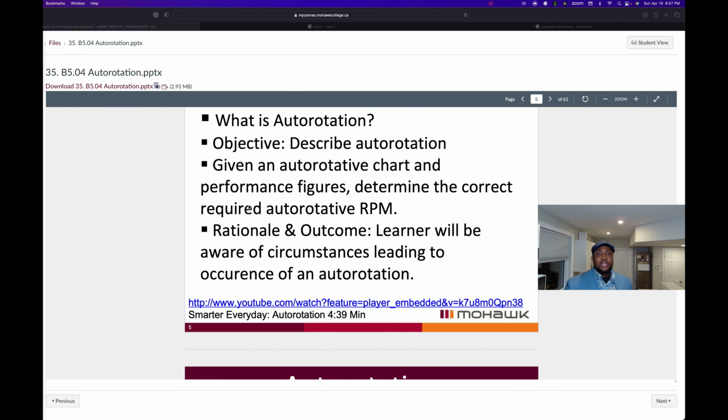This means that you have very dense air, and this dense air is good for the aerodynamic performance of your blades, and this will affect how much lift you're able to produce. Less dense air correlates with a higher density altitude. You have this issue where you need to avoid operation in a larger and larger area for continuous periods of time.